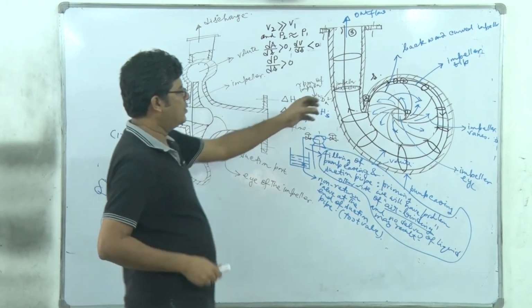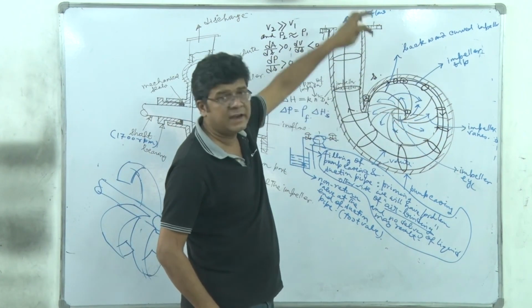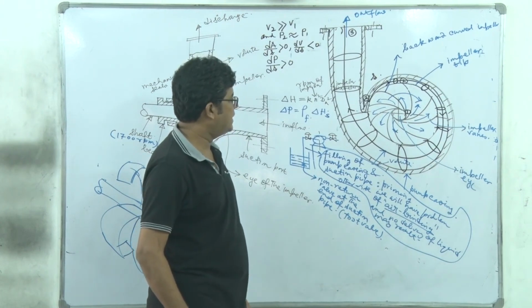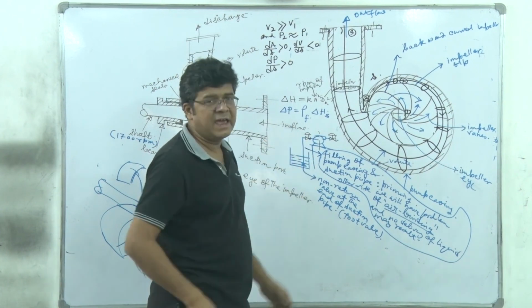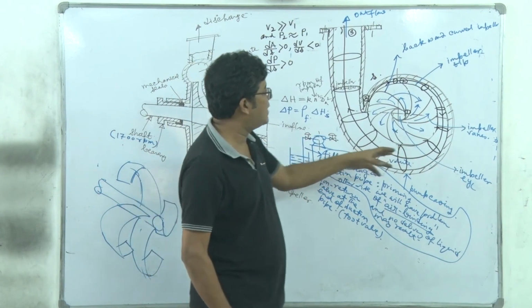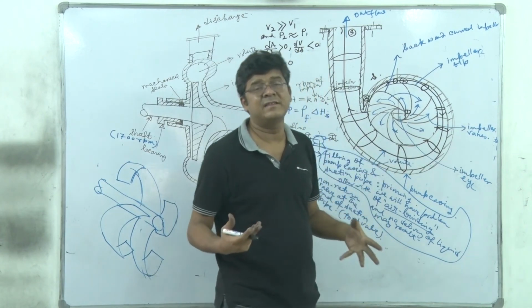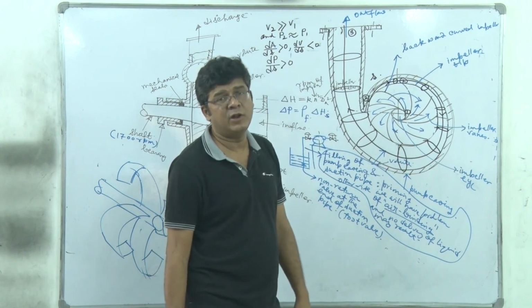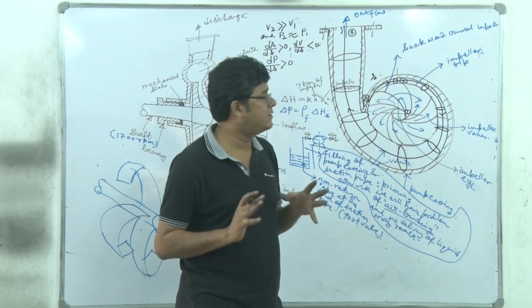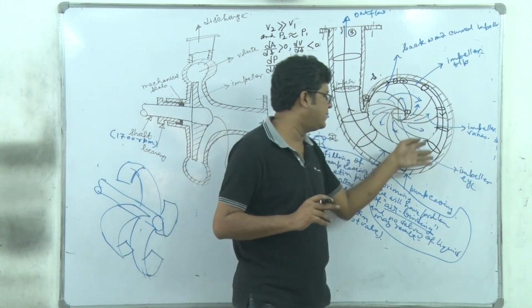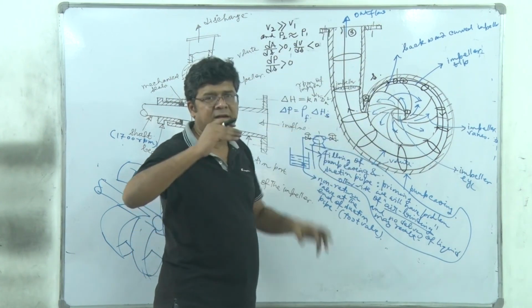So in this volute, the velocity head is progressively being converted into pressure head, right? However, the increase of this area should be very gradual, otherwise we will have inevitable boundary layer separation, formation of wakes and eddies, where part of that energy will be lost. So the design of the volute must be very intricate. It is actually intricate, but nowadays it has been standardized heavily, right? So this volute should be designed and it is to be tested.